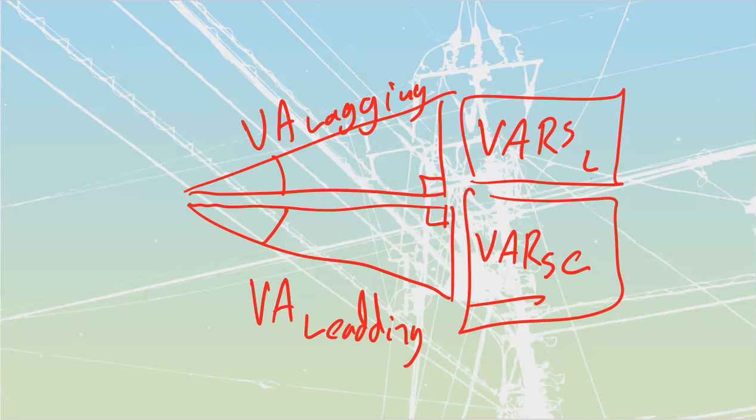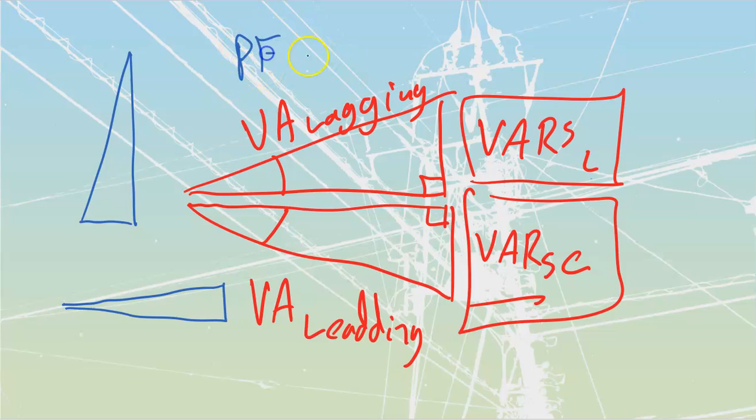There's also a number of example triangles that they give you inside there that just kind of show how we should be able to recognize something that's going to have a good power factor compared to something that's going to have a poor power factor. We know that power factor is simply my measurement of my watts over top of my VA. Hypotenuse is always going to be the VA, so if I'm looking at watts, which are always on the X, over top of my VA, I see it would only be a small percentage. Therefore, this thing would have a poor power factor and a large phase angle. This one over here, I see I've got a large amount of watts compared to my VA. Therefore, I'm going to have a relatively small phase angle and what we would refer to as a